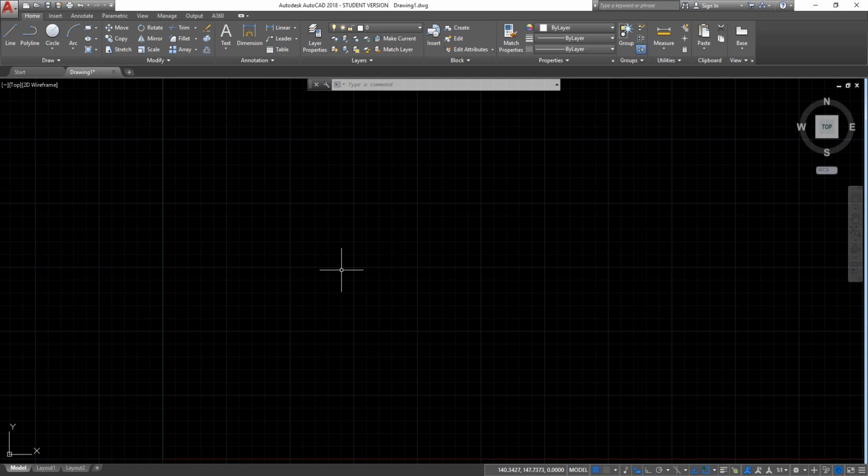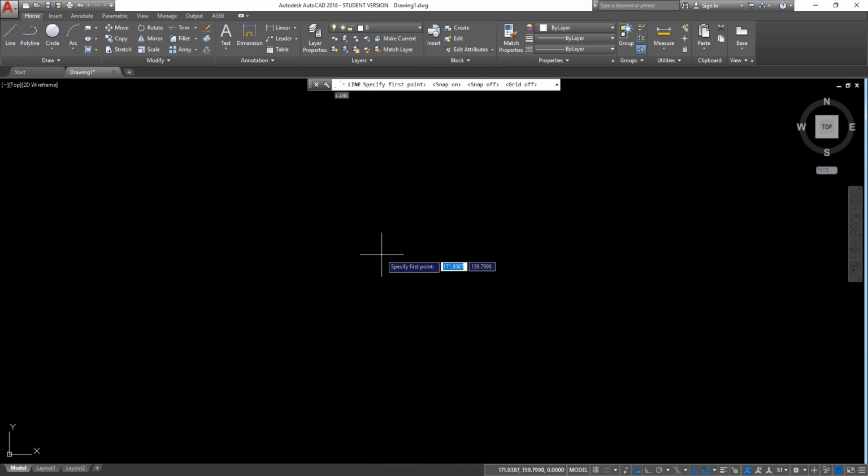If you're drawing and you have the snap on, the crosshair will jump to the intersections of this grid. But in my opinion, F7 is also obsolete. Okay, F7 and F9. F6 works for 3D modeling, so we are going to discuss it later.